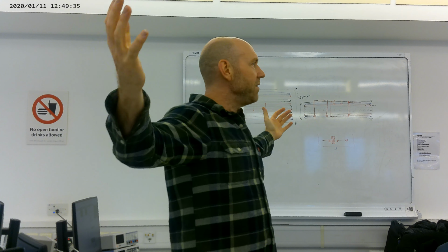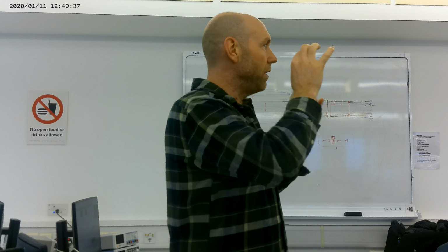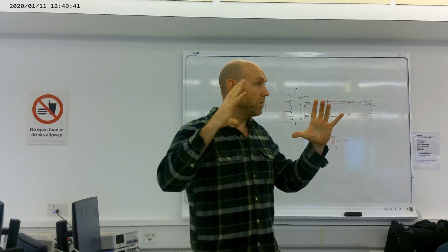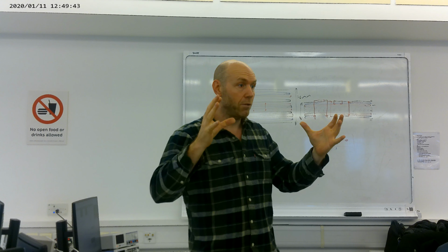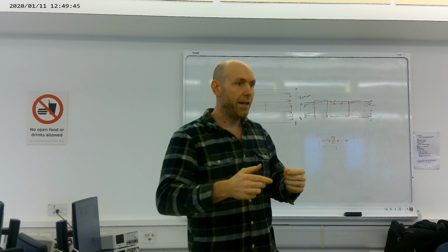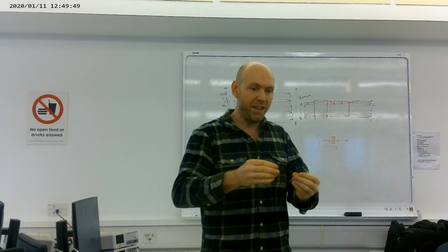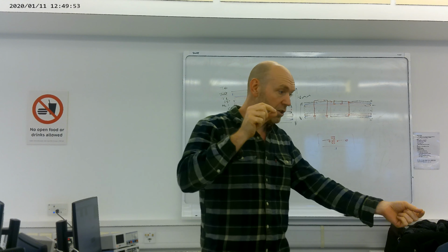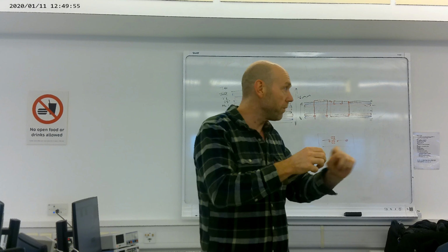If you can imagine, these are big machines. They're not going to want to put individual resistors in there. They normally use reels of resistors, which have got 5,000, 10,000 on a roll, and then your chips. If you've got an IC, a 555, it will come in a tube, and the tube would have, say, 30, and then you put that in the machine, and the machine would take the one off the end. That's how they work.